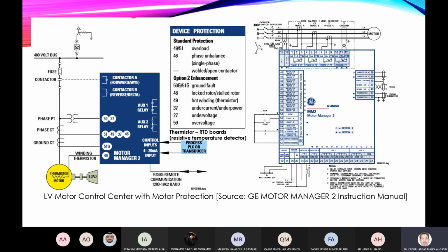And this is how you connect the CTs. So this is a fuse with the contactors, and these are the VT and the CT. The VT is required because you have under voltage and over voltage elements. From the voltage we can also check the phases and measure the frequency. I can also identify the sequence of the supply.